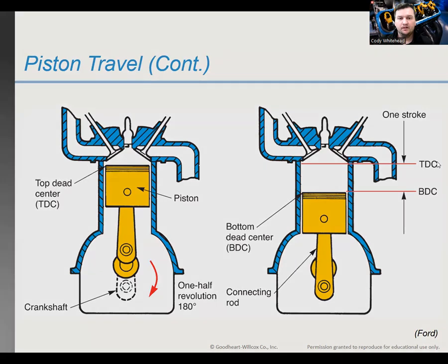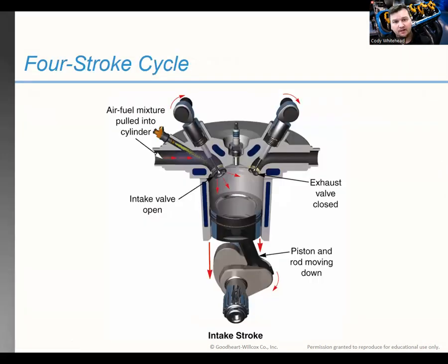All right, our four cycles. Most vehicles nowadays run on a four-stroke system or a four-cycle engine. We've tried in the past to use two strokes for vehicles, but it does not work. The oiling system doesn't work for a normal motor vehicle. Dirt bikes and stuff, it works fine for those. For cars, it just didn't work right, and they're a little bit more heavy on pollution as well. So four strokes is what we need to learn.